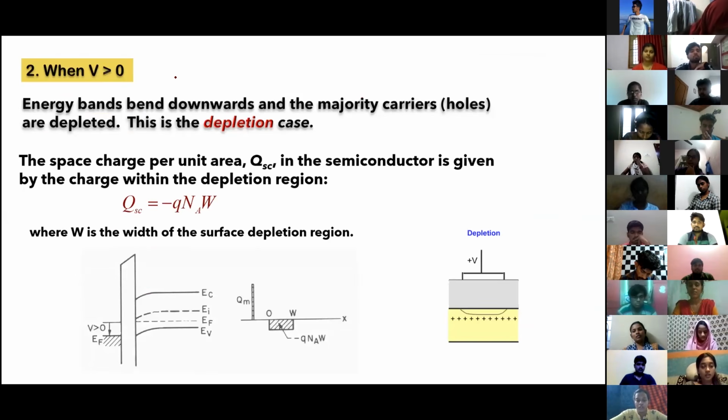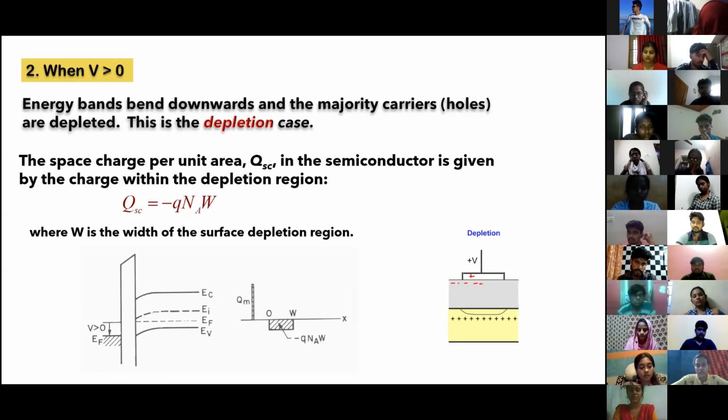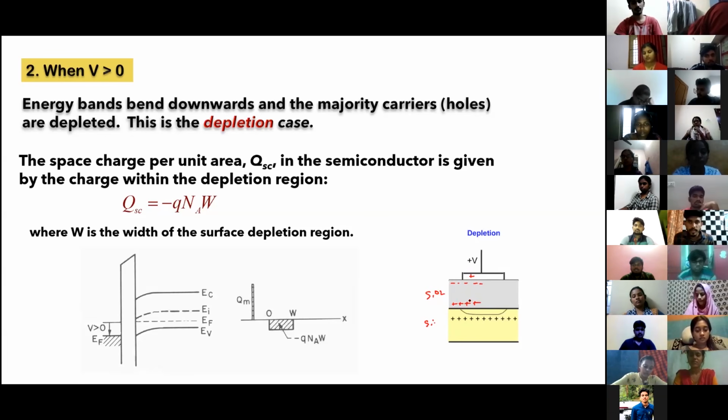It's not so positive, but a little bit positive here. When you put positive on the plate here, the side of the dielectric will become negative. This is silicon dioxide. This is silicon. Accordingly, a positive charge is developed here, and here the majority carriers are positive-charged holes. So this positive charge will push them away. It will say, come on, you are positive, I'm also positive, get lost.